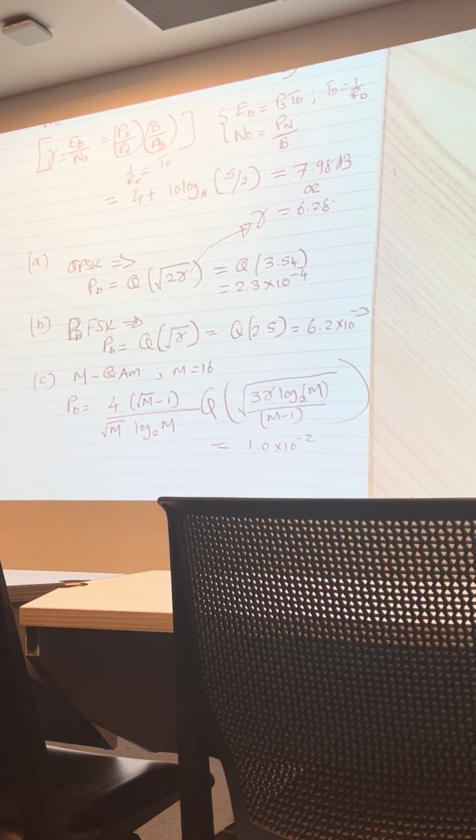So when you pack in more and more symbols, 16 symbols in this case, for the same energy circle in the IQ diagram, that means that differentiating between the symbols becomes a bit harder, especially with noise. So in that case, your bit error probability will increase compared to a lower value of M. Okay. All right.